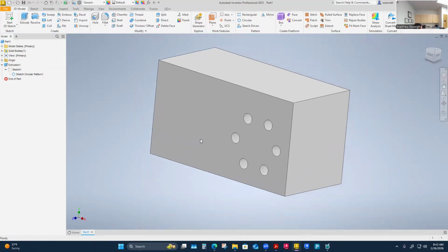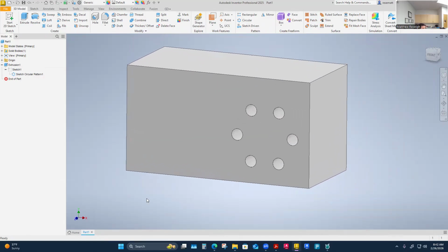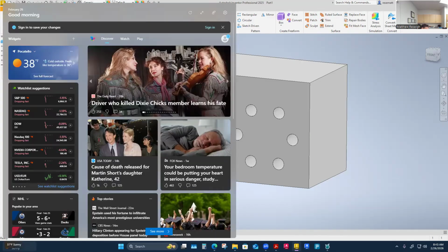It changes my extrusion just because that's not a selection of a hole anymore. And if you'd ever done that, if I had had that hole in there before, and then in some other sketch down the road I had projected any features of that hole, but then I come back and edit my sketch and change my features and I lose that, your projections will become pink in that sketch and they'll be lost. So you have to be aware when you're modifying your part that it's going to have kind of a domino effect on what you've projected from it as the model builds out. That'll affect this and the drawing that it goes on for sure. So maybe you guys have already experienced some of that. Once you delete stuff, anything that was built on it later down in the model is going to be impacted if you change it.